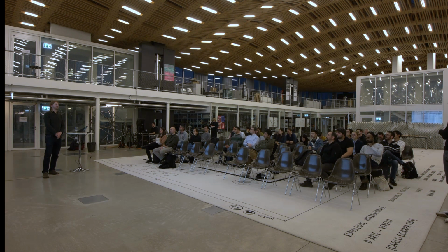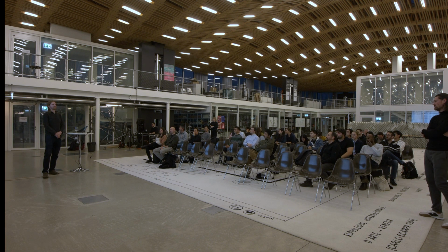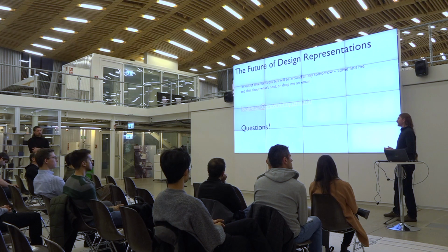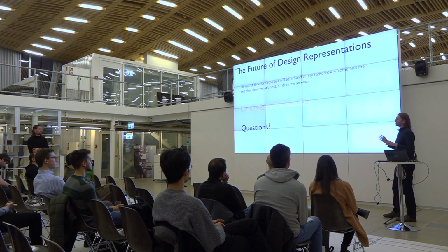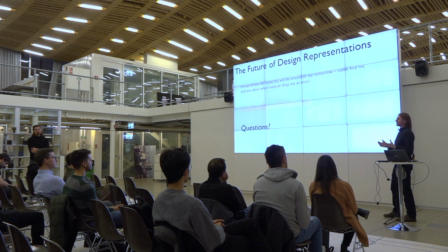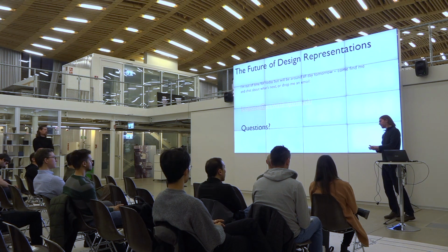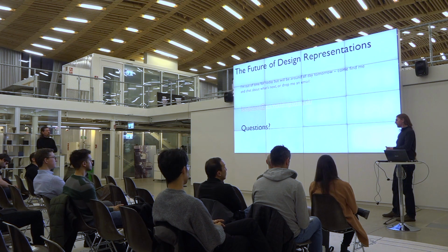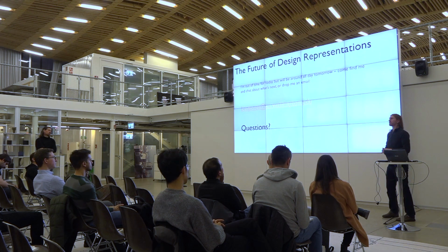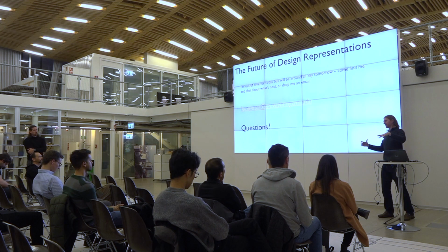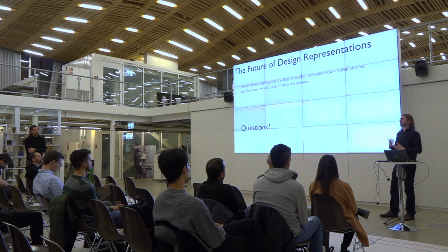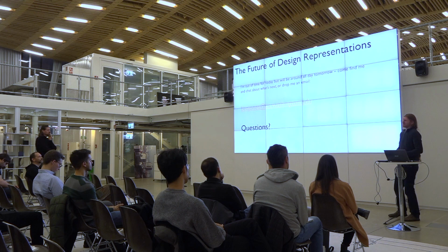We did some tests with using existing languages versus defining our own DSL, and honestly, it does just about as well with an existing language as our own DSL. The other thing was these kinds of constraints I'm talking about, what I'm calling layout constraints, like the legs are under the chair, for example. That is actually not something that's expressible in traditional CAD software. Most existing CAD systems, for their constraint systems, only allow for equality constraints. But the notion of something being underneath or to the left of, or inside the bounds of, are inherently inequality constraints, and the solvers built into existing CAD systems just don't handle those. And so we're building a language around those kinds of constraints.